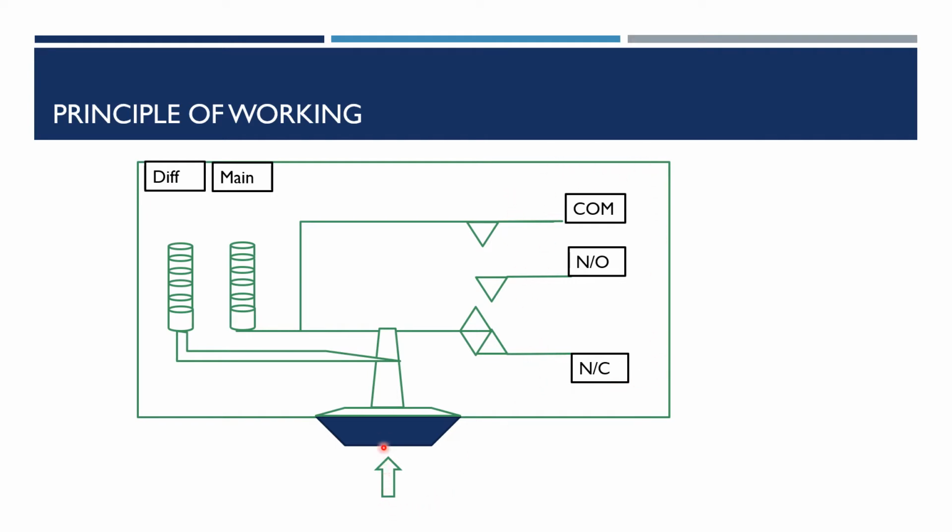And of course here we're gonna have the pressure inlet. This is where you're gonna apply your pressure. You're gonna connect your hose here, and inside this block we're gonna have some diaphragm that keeps the pressure until some level in order to push up the, let's say, nose of this pressure switch. So this is the typical element of the pressure switch.